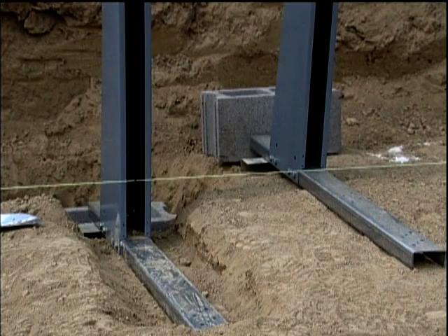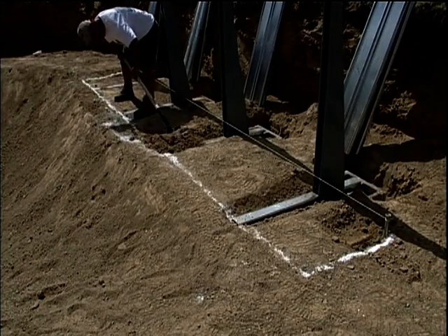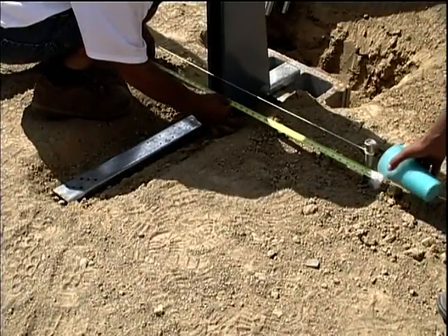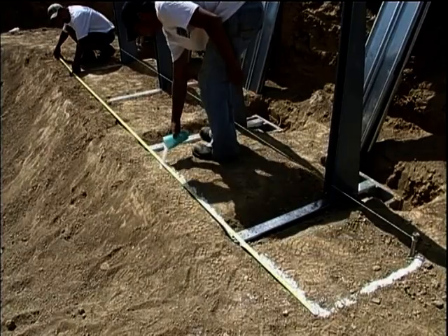At this point, the pool floor level should be 2 inches above the ground support channel. This area around the side vertical assemblies will need to be dug out to be level with the ground support channels. Be sure the vertical assemblies are even with the string line layout for the side of the pool. Measure 1 inch from the verticals and lay down a string line. Then measure 24 inches out towards the center of the pool.